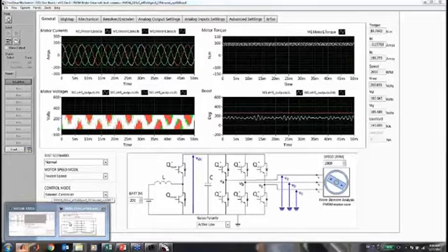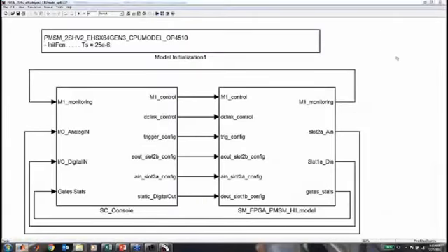As you might know, if you've worked with an OPAL-RT product before, the simulation is hosted in the simulator, which is a CPU-based simulator. But in our case, the CPU simulator is just here for the monitoring and to control the FPGA. Inside the master subsystem here, which is the one that runs in real time, in contrast to the console subsystem, which runs on my host PC for monitoring purposes,